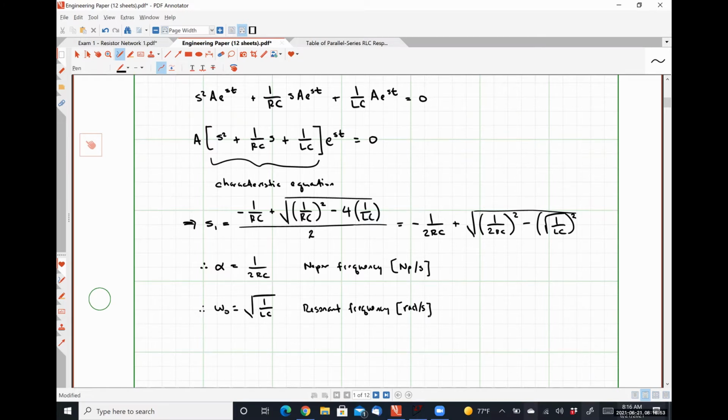It effectively broke itself apart because the wind started blowing at the resonant frequency of the bridge, causing the oscillations to have their maximum possible amplitude, which was enough stress to cause the bridge to completely and utterly collapse. Brand new bridge, huge project, literally billions of dollars thrown away over about two months. That's how new the bridge was when it collapsed.